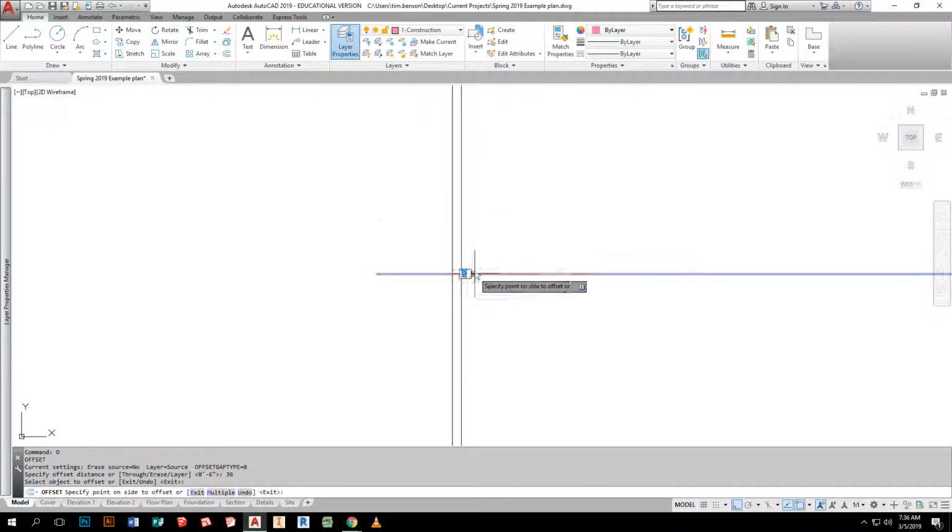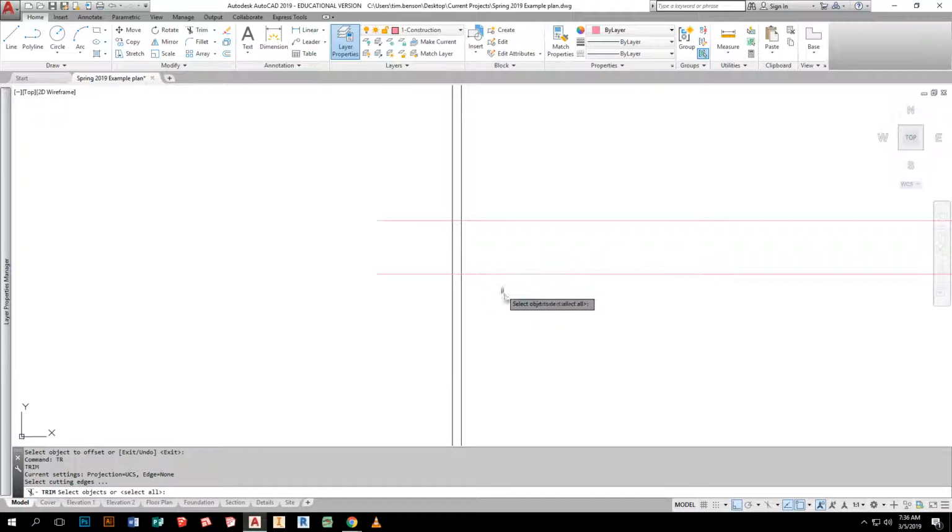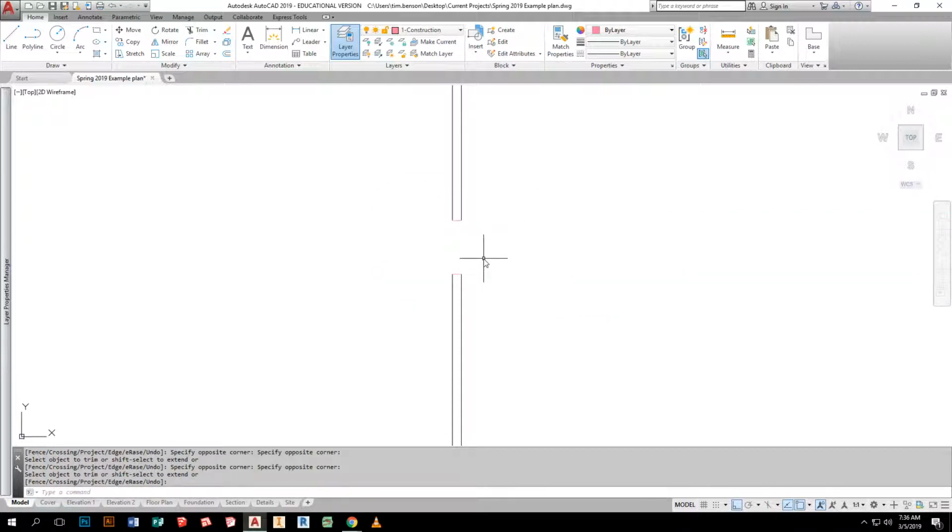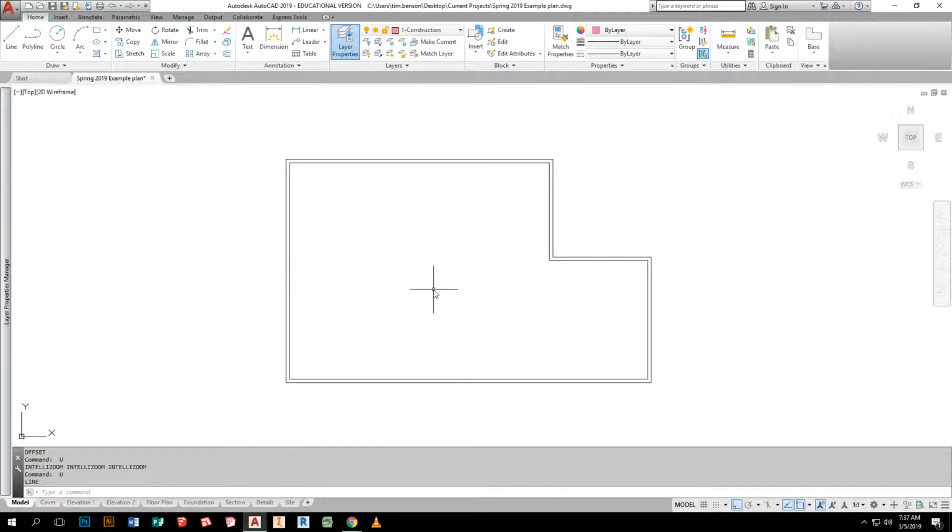Now, most doors, I draw just like that. Okay, now what I did is this. Let me go back here and undo. You get going quickly. I use my line tool. Draw a line straight off there. I snap that, bring it straight off perpendicular. I offset it, the 36 inches. That is the door opening.